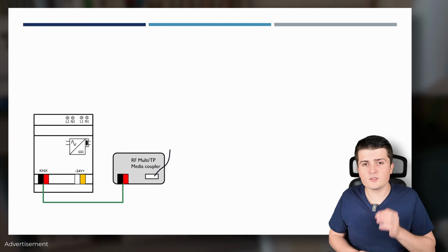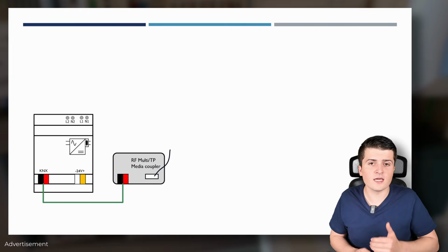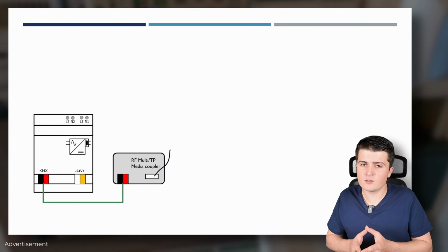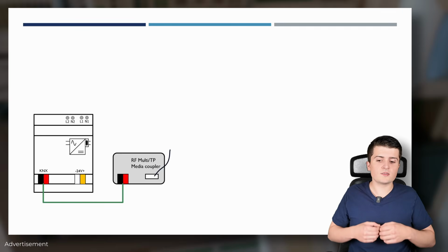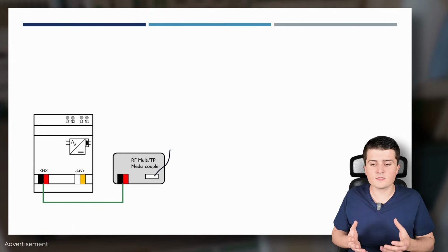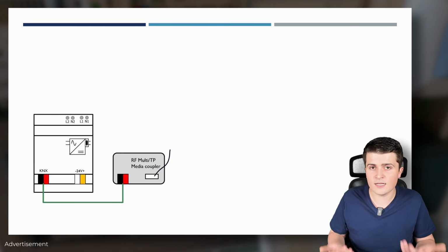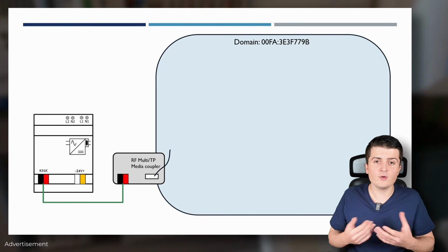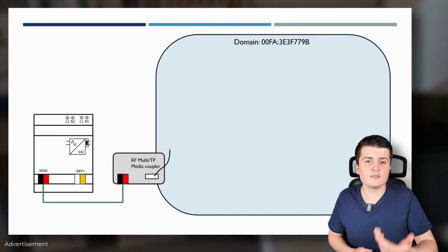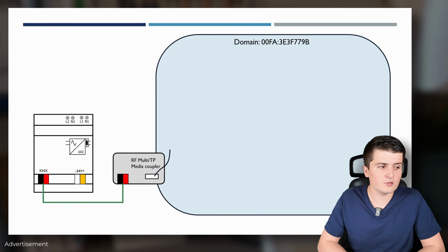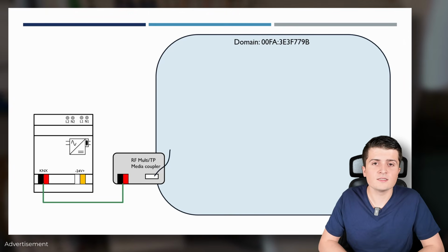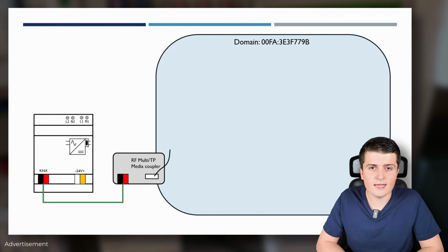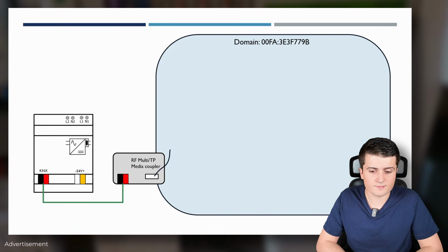And it's also important to know that you need to have this KNX twisted pair installation, or at least a KNX power supply with the twisted pair media coupler, because the media coupler basically opens or creates the RF network. As wireless is an open media type, we need a solution for that, and that's the so-called domain address or the domain. And this is created by our media coupler, which we'll also see later on in the ETS.